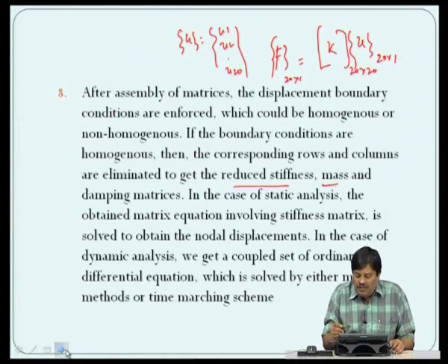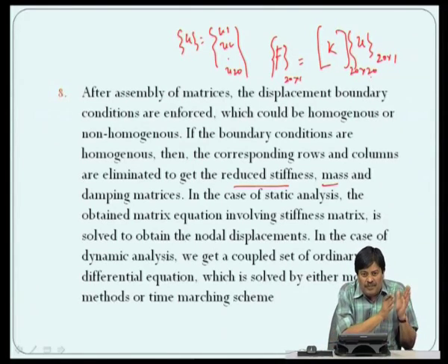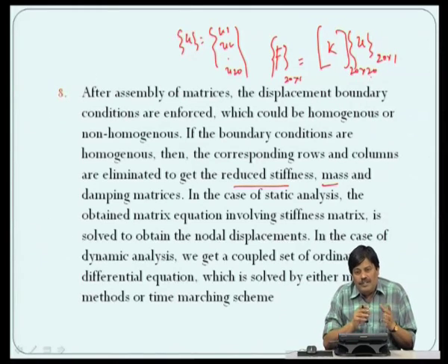So, the resulting equation will then be solved using the standard algebraic solution methods, and we solve for the displacement. Once we get the displacement, we now use the elemental equation for each element, f equal to ku, then get the forces and hence the stresses, and whatever quantities you want beyond displacement can be got by post processing the results.